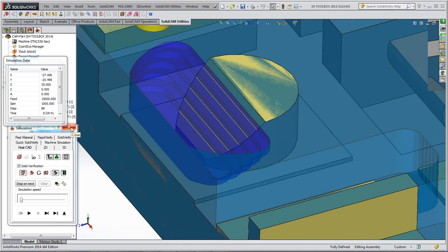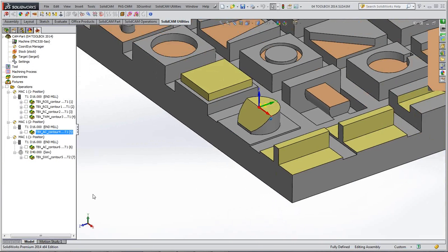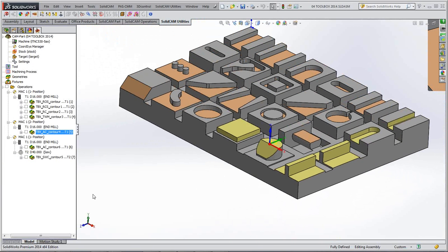Obviously that's stepped out. You probably want to finish that so you can run the same cycle again but with a much closer step down value to get closer to form. Another little handy cycle.